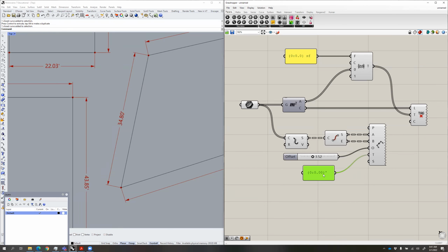So now you can annotate this in such a way where it has an actual unit value associated with it. Or if you don't want to have 2 decimal points, you can just do 1. Depends on how much precision you're willing to give up to the contractor. And that's all in that decimal point right there. So, 2 decimal points for a length component may be too much.